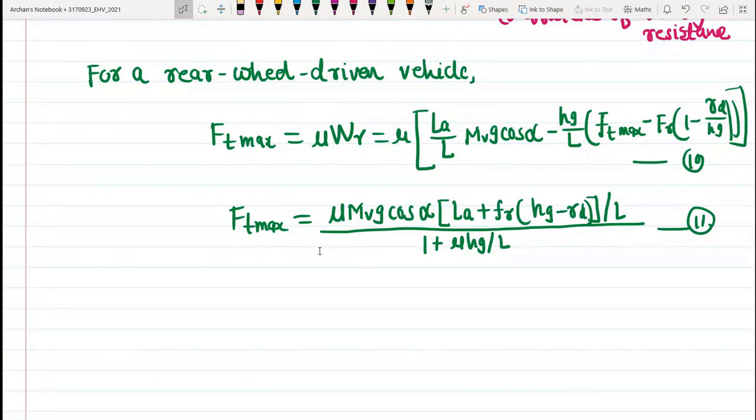Lots of experimentation has been done, and the results show that on various types of ground, the maximum tractive effort of the drive wheel closely relates to the slipping of the running wheel. This is also true on a good paved dry road, where the slipping is very small due to the elasticity of the tire.